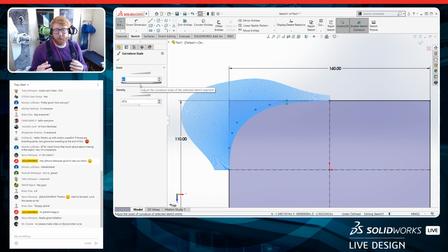So the really cool thing about a style spline is none of those vertices are actually on the spline itself, right? It's actually this chain of control vertices that's controlling where the spline is. But because I'm not changing those individual points on the spline, it's this single span curve, right?